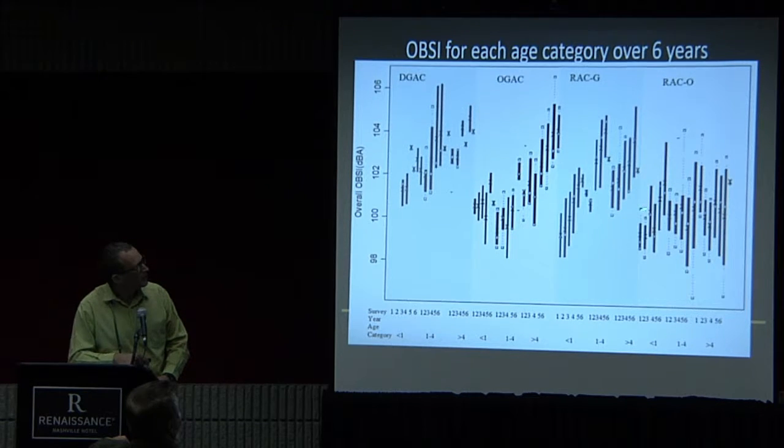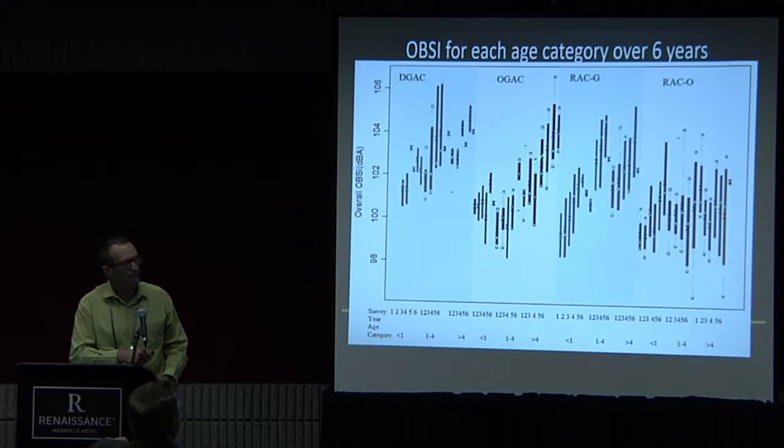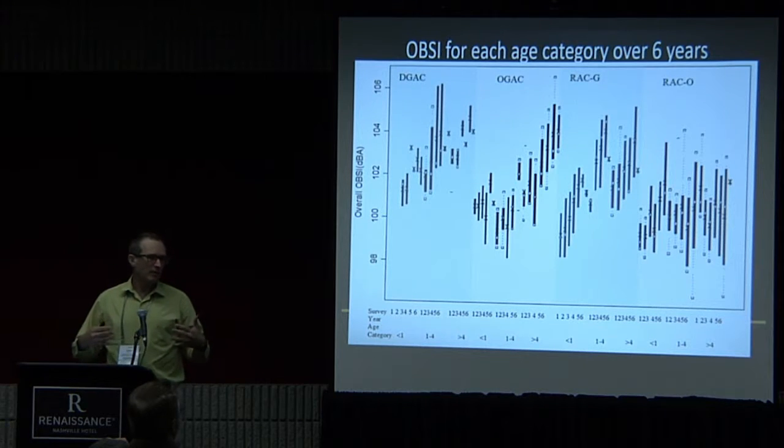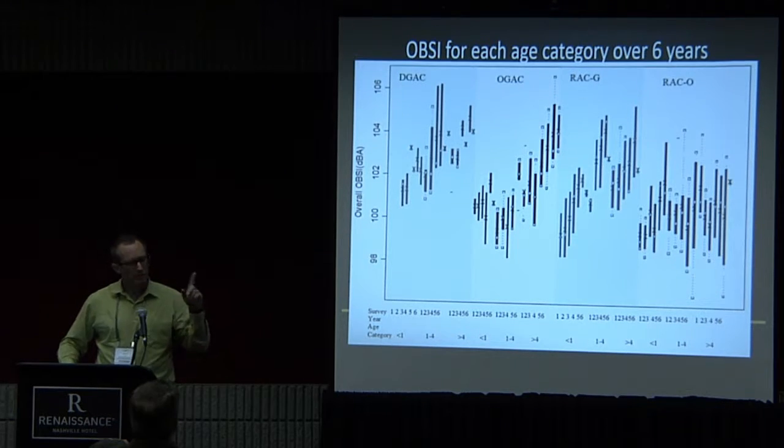Main reason that the rubber stayed quiet, open graded, and the conventional and the few polymers in here didn't, is because the rubber didn't ravel, and most of that noise increase in the gap graded is that it ravels somewhat faster than our rubberized, and that's why we believe that the rubberized open graded is staying quieter over the long run. It also didn't reflect the cracks as fast. Cracks actually will give you spikes in noise.